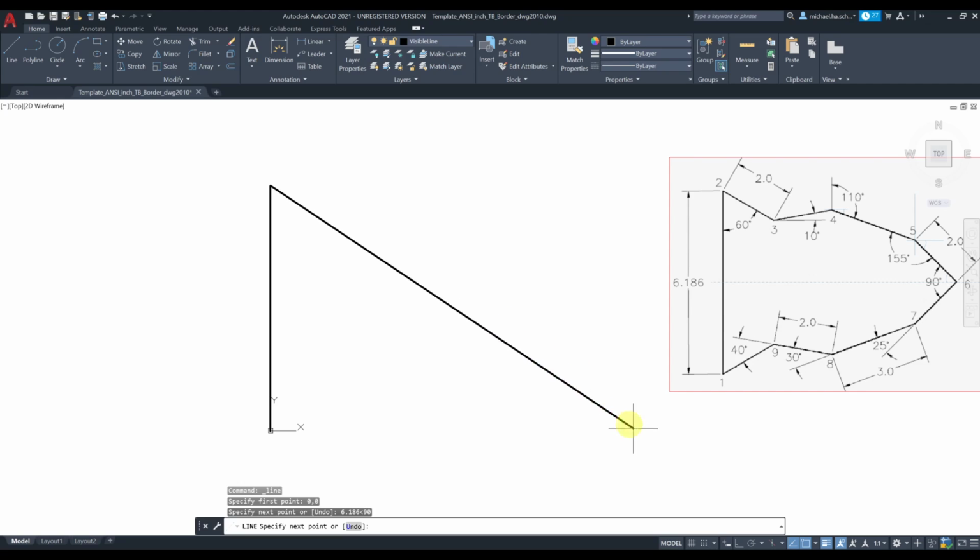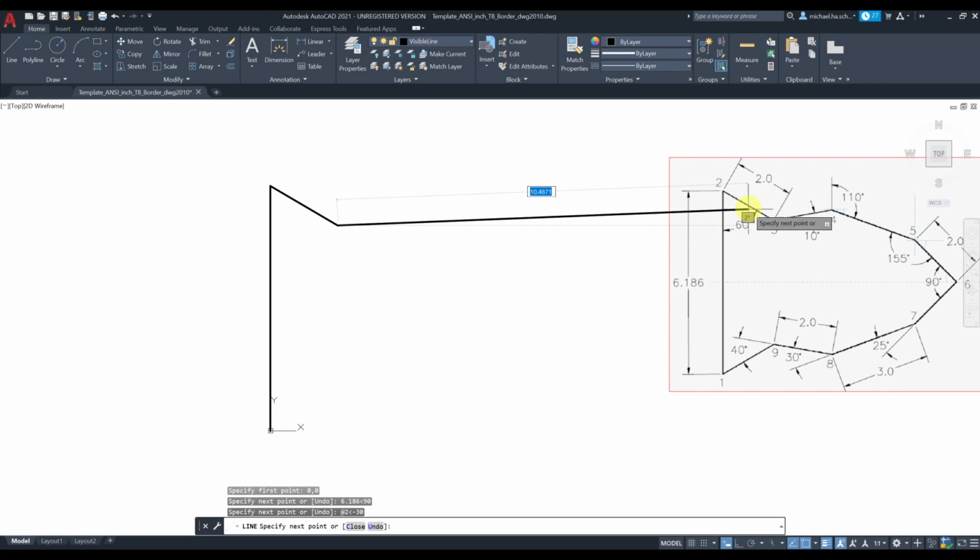Okay, the easiest way is to turn on dynamic input. As you see next to the cursor, you're going to have your two spaces. With the tab key, you can switch in between those two. So the length is 2. With the tab key, you can press the angle. What you can do, -30 or 360 minus 30. 330, you can do either one. So we're gonna do -30 for that. So that's 90 minus 60 though.